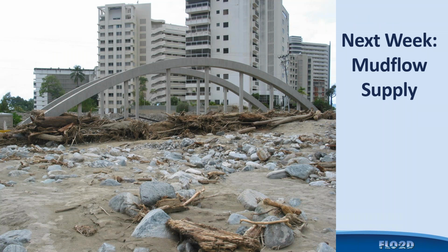Now, next week I'm going to talk about mudflow sediment supply. Obviously, the mudflow component in Flow2D is important because people use it for modeling tailings dam breaches. And one of the things that we are starting on now is a two-phase flow model so that you can run the Flow2D model with a storage of water over top of sediment, stored tailings dam sediment, and have it flow both as highly concentrated conventional sediment load as the water drains from the tailings dam reservoir if there's water sitting on top, or as a mud flow underneath the water until the water's drained away from the sediment.